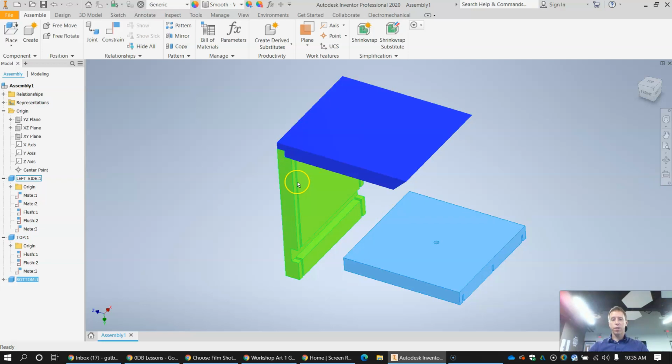So for these slots are an 1/8 inch thick. The technical drawing only shows 2 decimal points. So it rounds up. So 1/8 has decimal points 0.125. On the technical drawing it says 0.13, which we discussed in class. Like, you have to use the proper numbers. It's not a big deal. You just go back to your part and fix those numbers. So if you typed in 0.13 for the thickness, go back to your proper sketch, change that to 0.125.